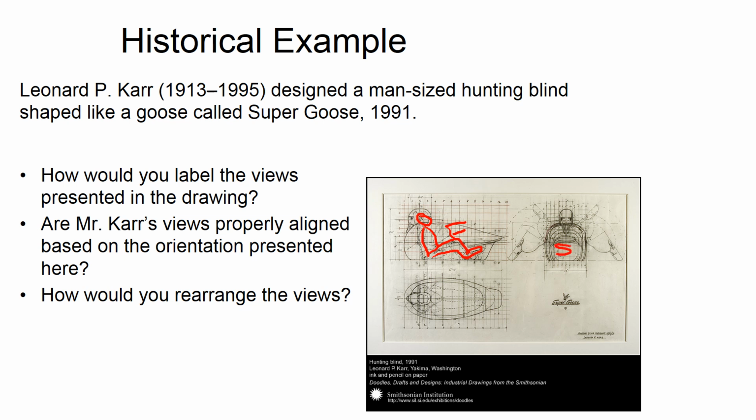This makes the side view, and you will notice that these are not hidden lines, so he's actually got this turned backwards, and then this needs to move up to the top view where it belongs. So he's oriented these incorrectly in space, and then he's turned them incorrectly. Be sure to watch out for that as you build your own.